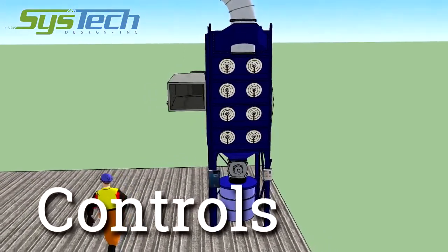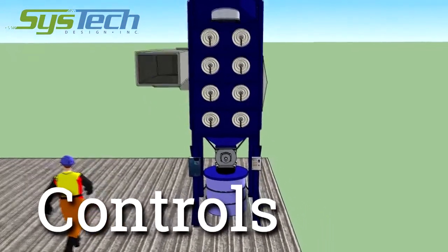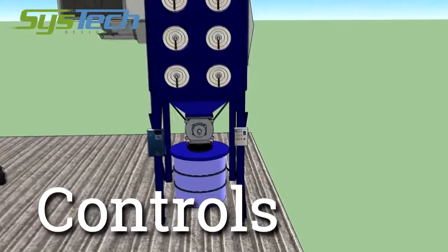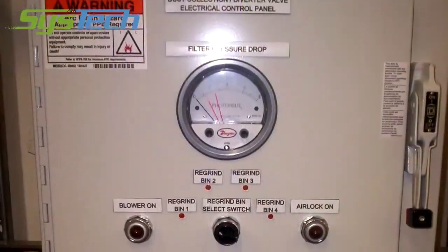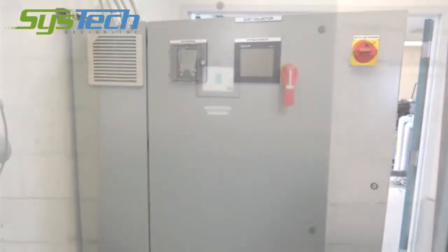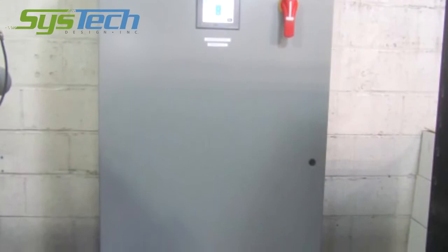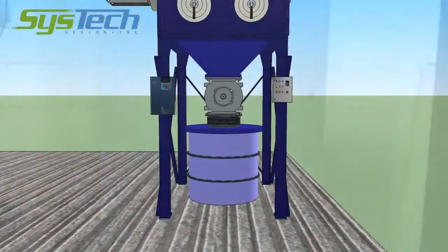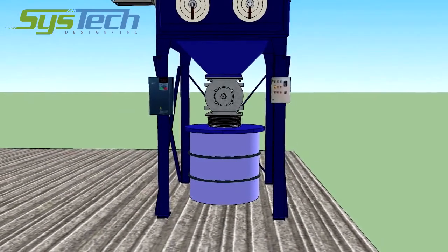The fifth C is controls. In addition to controlling the fan motor through a variable frequency drive, the panel should include pulse cleaning controls and system diagnostics. Cleaning the filters only when required extends the life of the filter media. Furthermore, simple controls with touchscreen diagnostics minimize maintenance requirements.